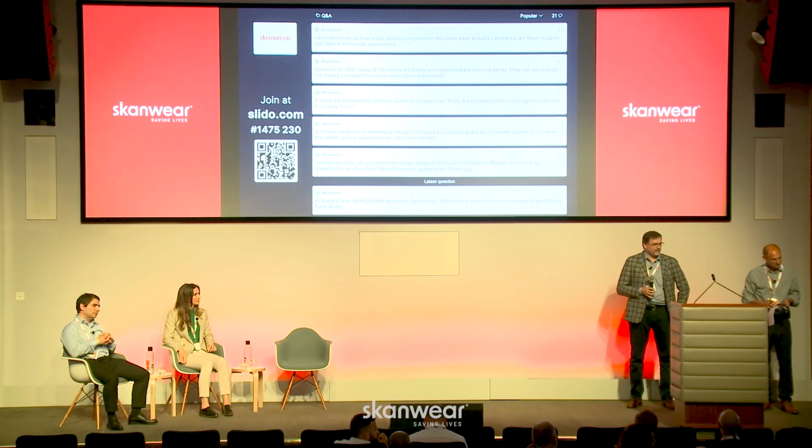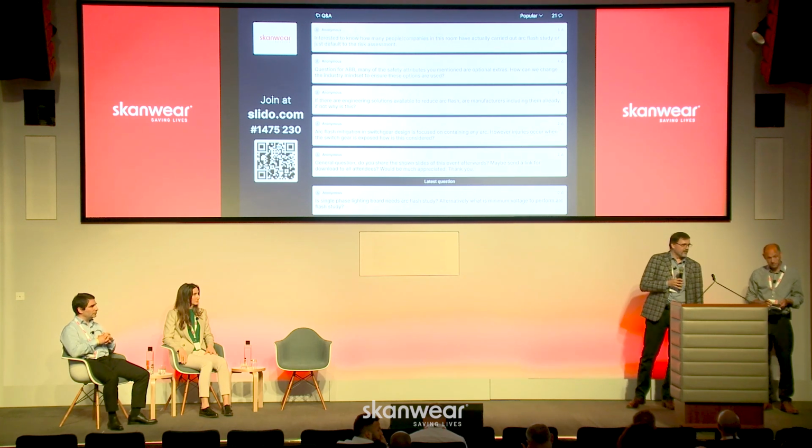Following on from that topic, why can we not do really tangible improvements to ensure that people aren't inside the enclosure to verify the state of the enclosure? Things like designated test points outside of the enclosure for points of verification aren't expensive solutions, but they keep people out of the environment in the first place. They can guarantee that there's no energy present from outside the enclosure. So why not just do that? It's an engineering solution that circumvents loads of this requirement.